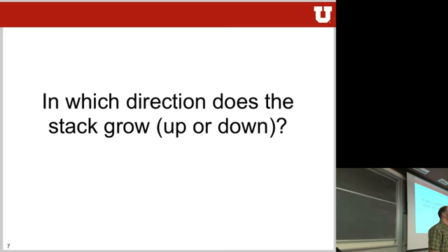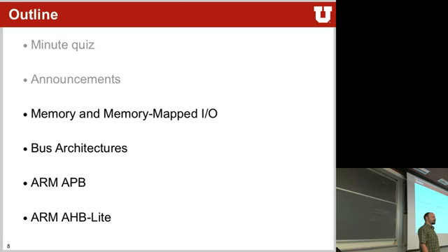When would you want to change the linker script? I would think there's something like when you're writing the BSP or something on the code, right? It's not very often that we need to. Yes. No, usually you don't need to touch the linker script, especially not if you get an environment for a microcontroller that's already set up. But sometimes if you start a new environment or a new project or a new platform, you have to write the linker script yourself. But what you oftentimes can do is take somebody else's linker script and change it the way you need it.